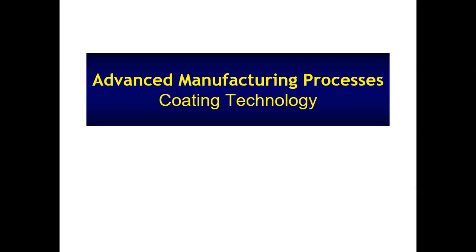The various colors of the cutting tools are actually due to the coating. Some cutting tools have a substrate material of carbide, maybe tungsten carbide. Sometimes it's high-speed steel, but it has a different color, and the color is due to coating being applied on the surface of the substrate.